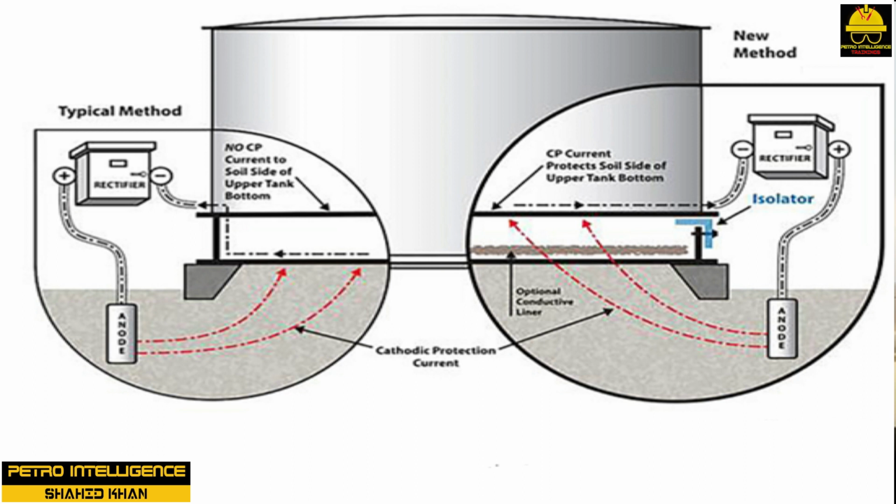Cathodic protection utilizes two different methods. Use of sacrificial anodes. Use of impressed current anodes. In both cases, the anodes are placed under or around the tank. Each anode is attached securely to the tank. Sacrificial anodes corrode in the place of the tank and will eventually need to be replaced, while the impressed current anodes do not corrode. When current flow is open, the system can protect the tank indefinitely.